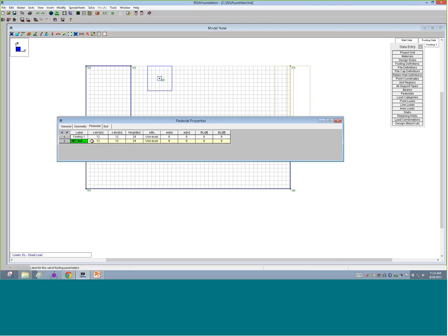You can also do some things like setting an eccentric. I like to sort of demonstrate this. If you have an eccentric footing, you might set this up to be a 12 by 12, but it's offset by 12 inches in both directions. So when you draw it, we'll see that that's actually going to be offset. You can also use a boundary type condition. So that boundary would be something like if you're up against a property line and you want to grow that in 2 different directions, you can set your boundary up there.